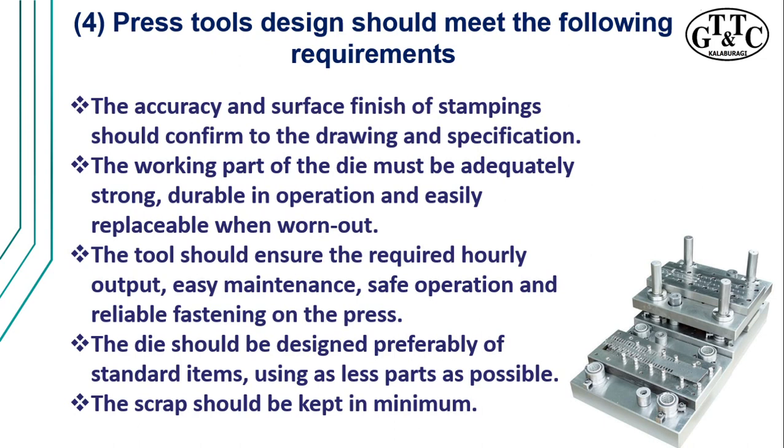And then finally, the scrap should be kept to the minimum, whether it is manufacturing scrap or material scrap or excess material. The right extra material has to be kept for all the plates, and after the tool, even in the strip layout, the strip has to be very economical so that the minimum scrap is produced.